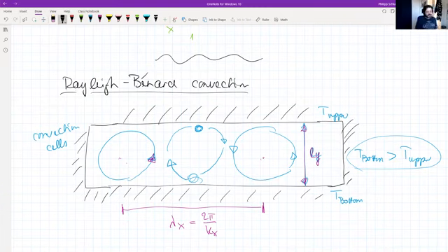But in order to make it as similar as if you had walls that are very far away, we consider here to have adiabatic walls on the side. Adiabatic means that the gradient of the temperature is 0 at that wall. So there is no heat flux that goes from the domain out through that wall, or vice versa. So that's one way of imitating a very large domain.